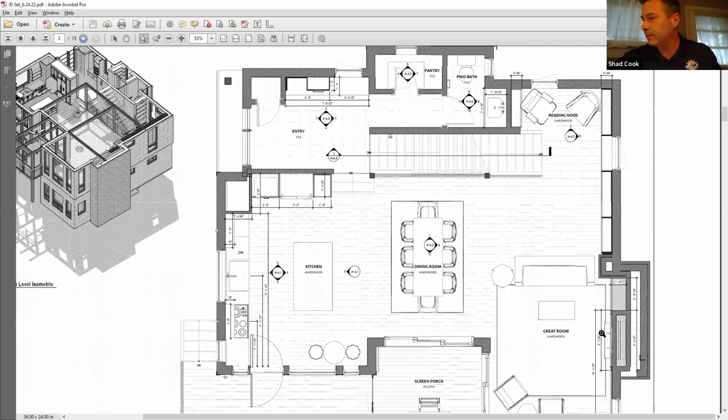Yeah, John, your Manual J calls for a little over 600 CFM to enter up into that bedroom, office, closet and restroom area. So obviously, if that's the only path we have to get up there, we're looking at probably about a 12 by 12 or 12 by 10 duct can probably get by and do it. Other than the fact that it is the absolute longest route you could possibly take from the starting point of the equipment to the end point of the home, I'd probably want to ask for 12 by 12 just to lessen the static pressure. But that's what we're looking at to try to get a duct up into that second floor area, or some equivalent. And you could change the aspect ratio a little bit to maybe 10 by 16, something along those lines.